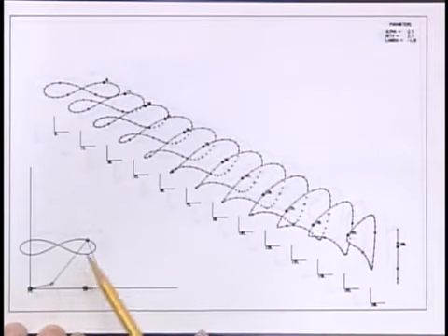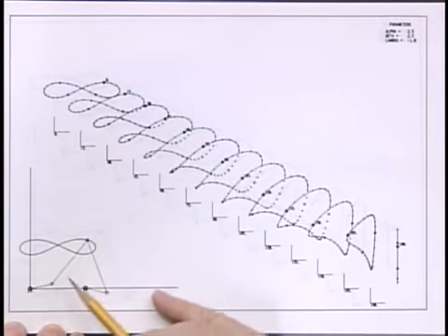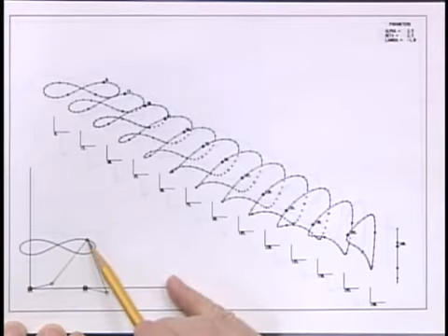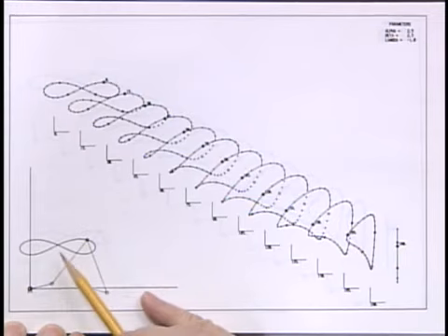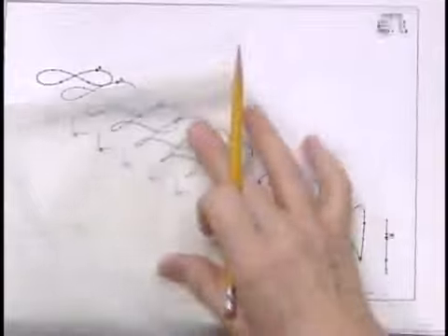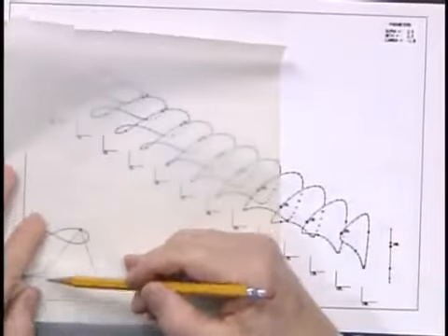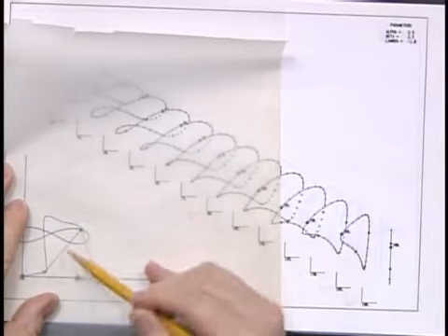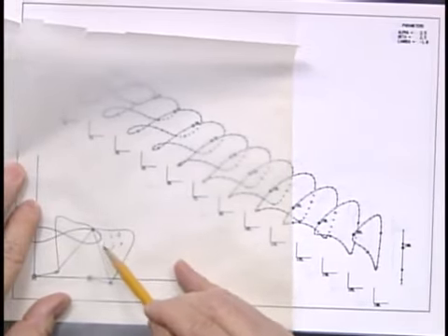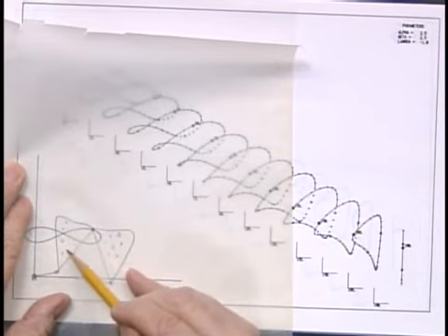This shows you the linkage down here in one particular position. That would be link 2, the crank. This would be link 3, one of the couplers. Link 4, one of the couplers. This atlas also only shows you curves at this join between the 2 couplers, and recognize the fact that I could put, let me get a piece of tracing paper, I can expand either of those links to include a whole bunch of other points, so I can get a lot of variety, and I'm not going to show it to you today since this tape is running too long already.